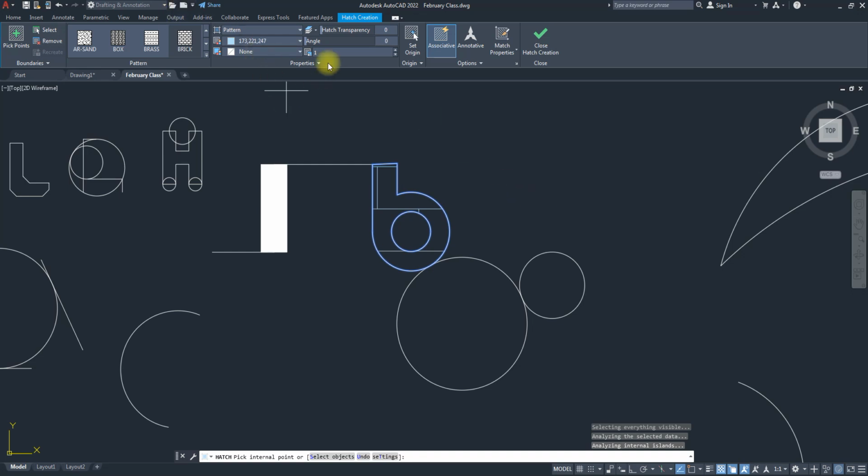So what I need to do is come down. That's where we can now start talking about all these things. We need to come to the scale option, which is the last option there, to scale this down. By default, 1 is what we have. If we start bringing the scale down, 0.3, you begin to see the pattern coming up. I think 0.3 is still too large. So if I come here and say, okay, I want 0.15, we are now seeing that pattern.